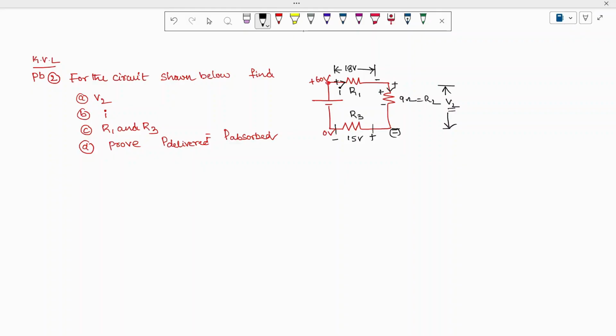Now I'm going to apply Kirchhoff's voltage law inside the loop. This is called a loop, or a mesh. I'm writing this KVL with respect to the leaving terminals, so that it is clear what I'm solving. The current is leaving, and the leaving terminal of the voltage is plus 60 volts.